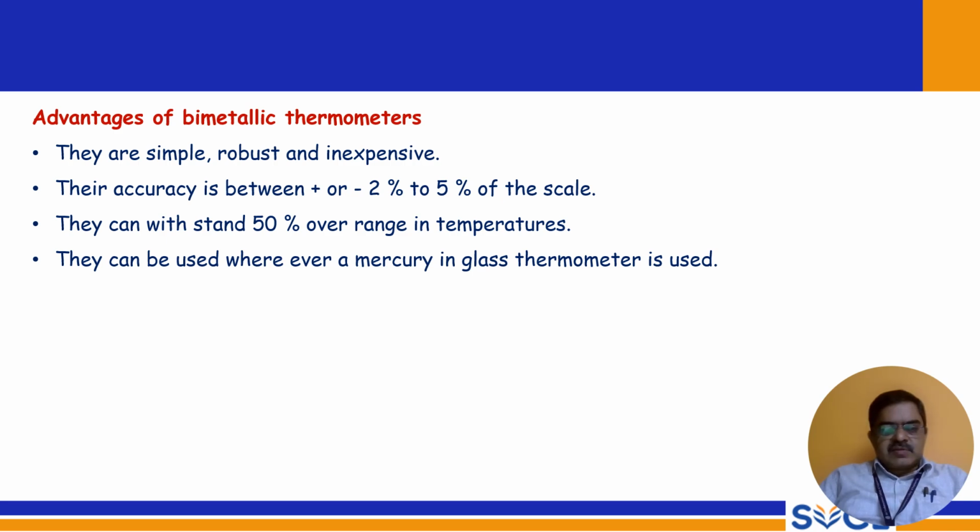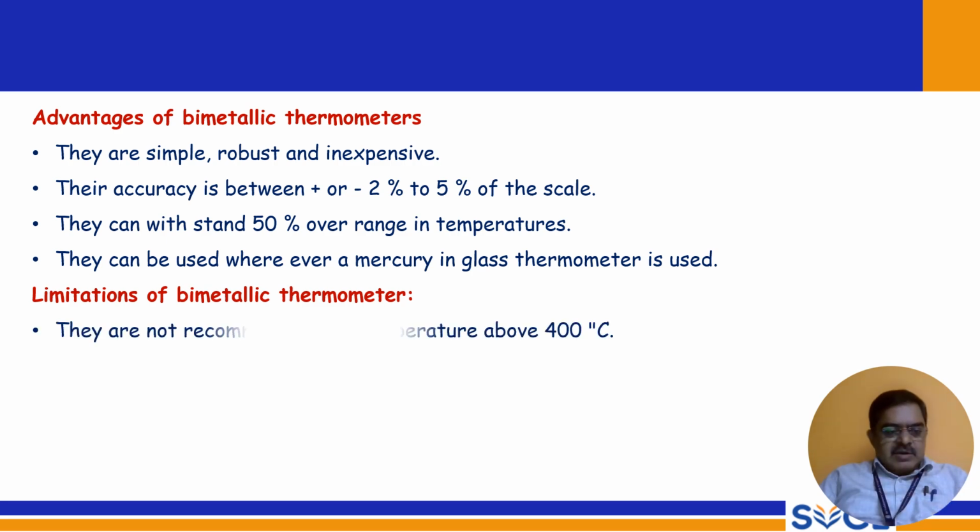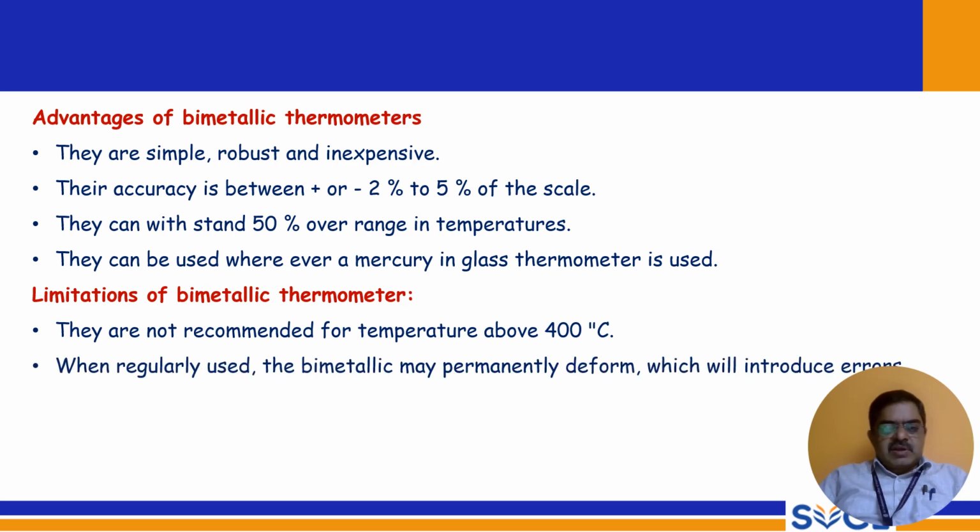The disadvantages are that they are not recommended for temperatures above 400 degrees Celsius. When regularly used, the bimetallic strip may permanently deform, which will introduce errors.